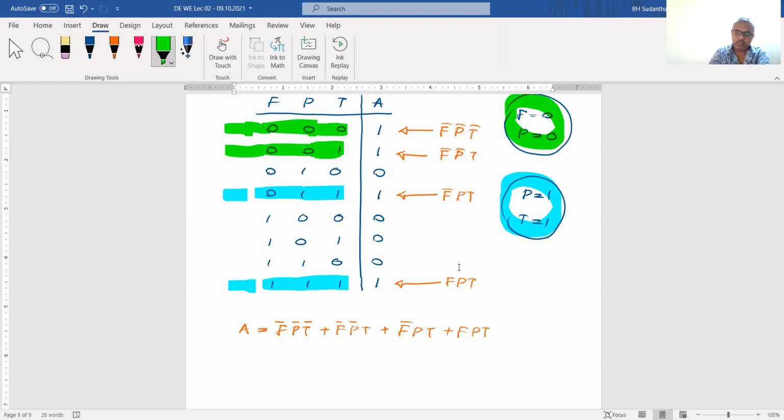The next step is converting those ones into terms. You know how to convert those ones into terms. Then after having those terms separately, you know how to write the Boolean output equation combining all these separate terms together. Then according to that Boolean output equation, you know how to draw the circuit using Boolean gates, the basic logic gates. So far, that is the summary. At the end of these 2 days, if you know all these things and are comfortable with all these steps, that's what we are expecting.